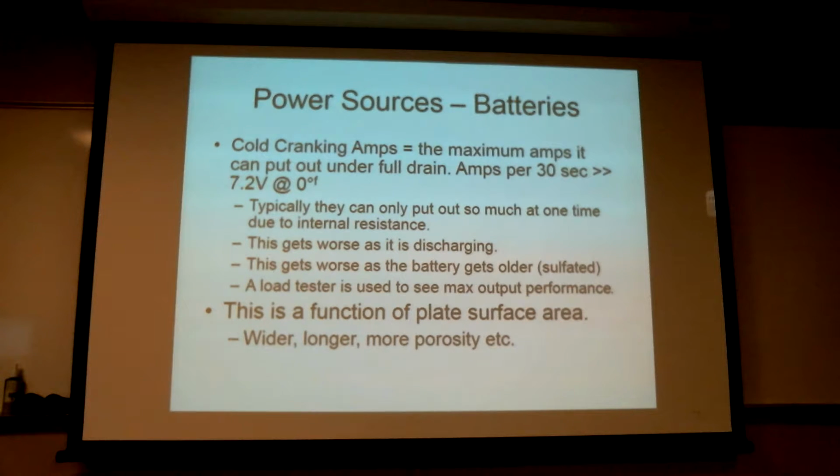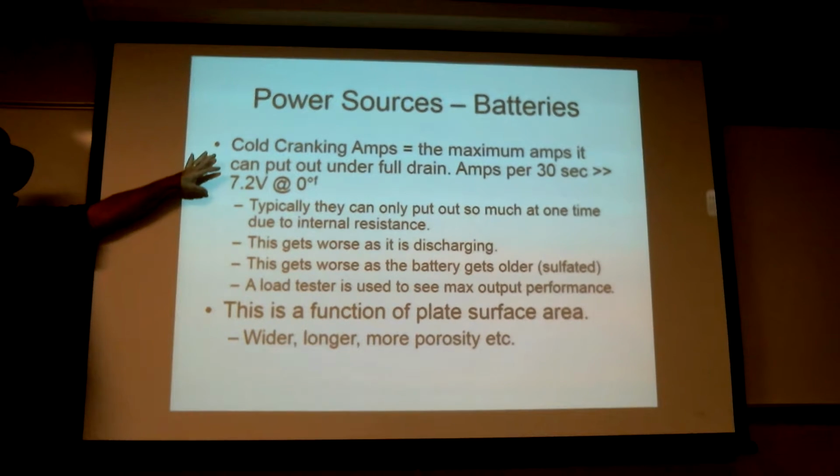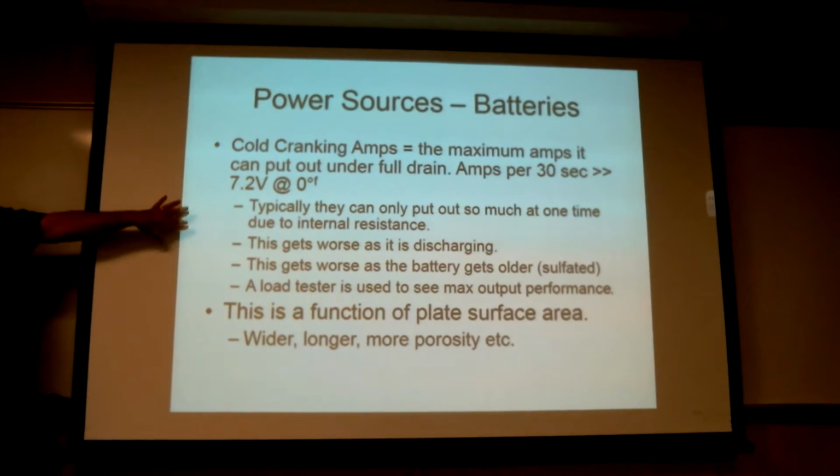The problem is it will be so fragile that if I deeply deplete it, it'll have a tendency to disintegrate pretty quickly. It'll crack and fall apart. So if I design the mission profile around high cold cranking amps, I'm going to say, great, works well, but don't ever take it more than about 25% discharge.